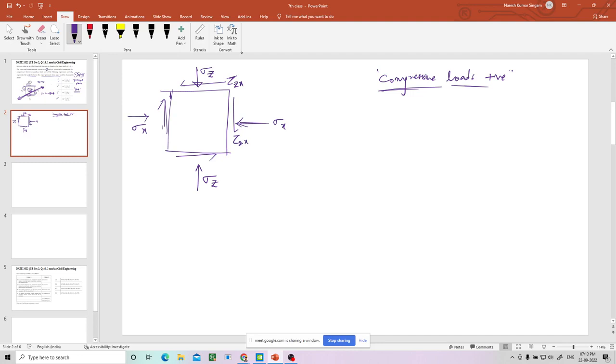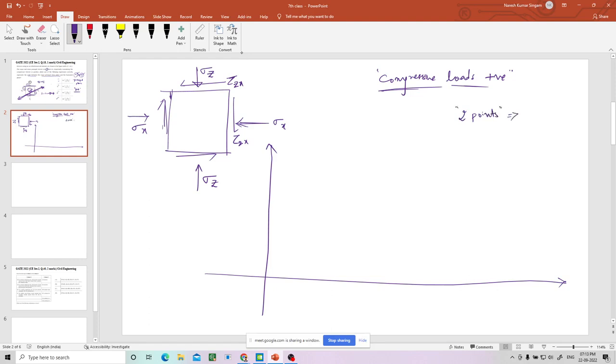So now what was the concept of drawing the Mohr circle? To draw any circle we need 2 points, and those 2 points should be the ends of a diameter. So here, what are those 2 points? Generally, for a soil element or any element subject to stresses, you have to take the 2 planes which are perpendicular to each other.